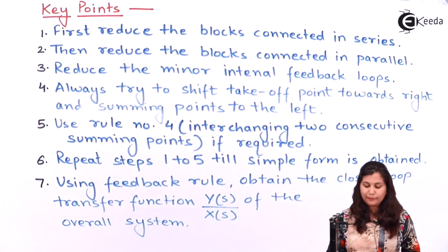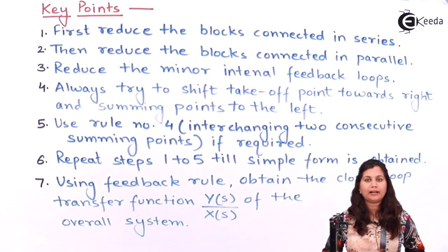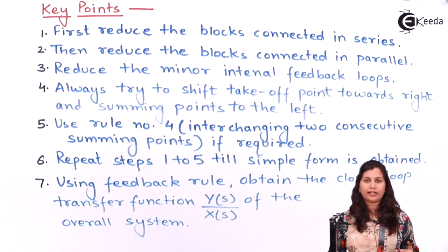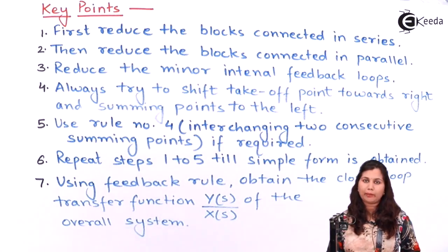In the second step, reduce the blocks which are connected in parallel. When the blocks are connected in parallel, you just add the transfer functions.